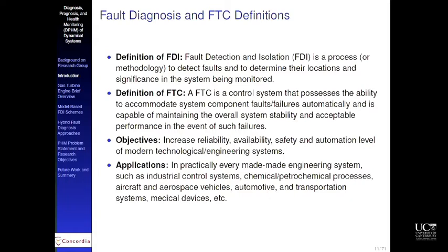And that's the problem of fault tolerant control. You need to go back and change your control laws and control strategies based on the information that you obtain in the diagnosis phase. Depending on the type, location, and nature of the fault, you need to reconfigure and recover your control laws to compensate for the loss of performance to the maximum level that is feasible or achievable for this problem. So these are the general questions that we need to address in any kind of research in this domain.